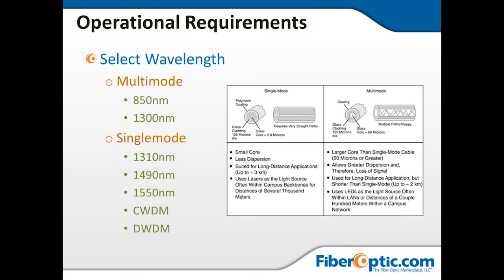Recently did a project that was just that sort of thing. We couldn't even get SFPs that were low enough in transmit power to not saturate our receivers. On the receive side, we had to pad it down, but it works famously because they had the ability to go with a very high bandwidth that the multi-mode fiber could not have handled. So these are the sorts of questions you ask. These are the factors you take into account, and then you find solutions.